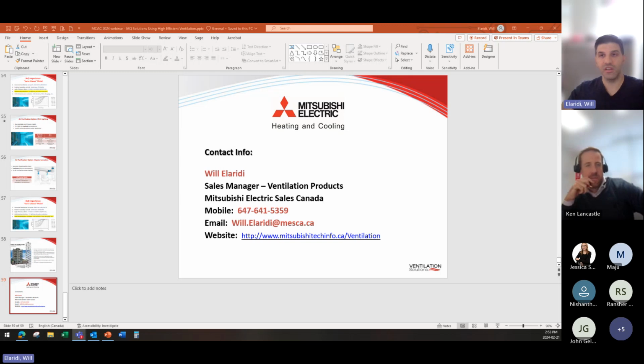I'd like to start from out to in, which is the building envelope. It really depends on the building envelope, how old the building is, and simply asking how tight are these windows? Is it double pane? Is it triple pane? How many openings are there in the building, and even the basement, like how is the heat rising? So it's definitely a loaded question, but if you're looking at a brand new building, you are looking on average at around 10 to 12 years of seeing a payback for these types of situations. We have done some studies on that.